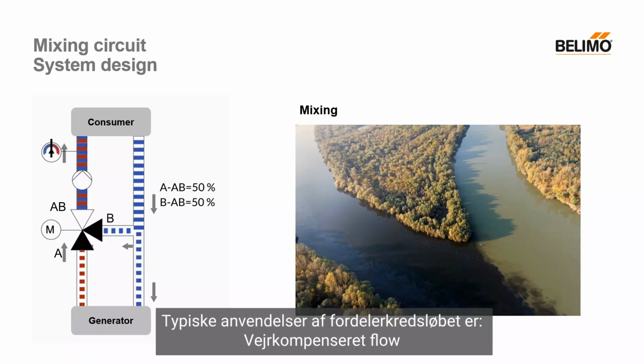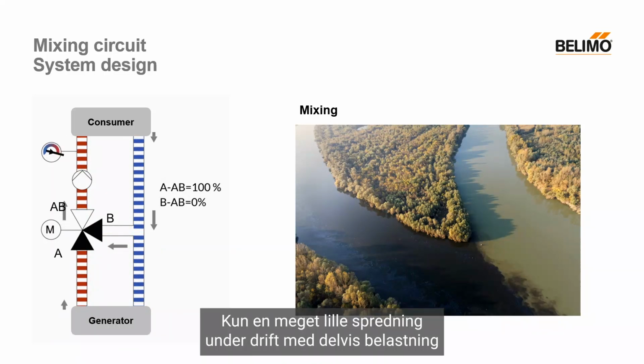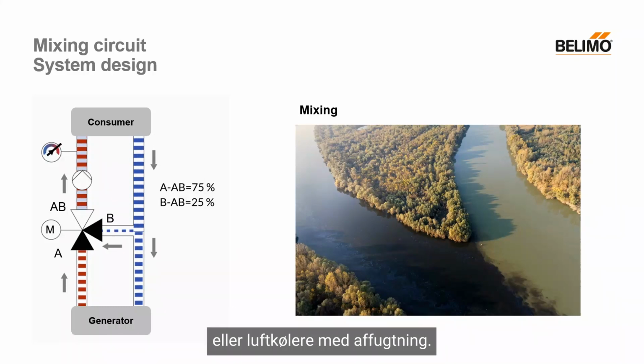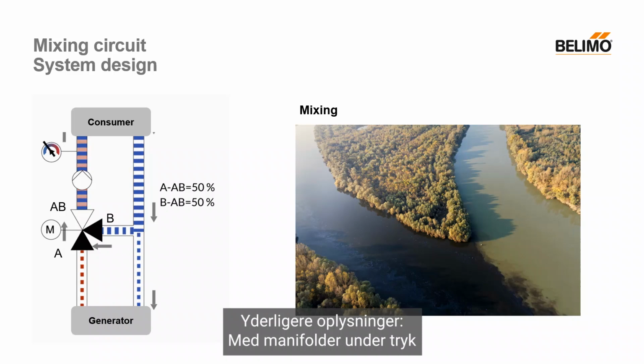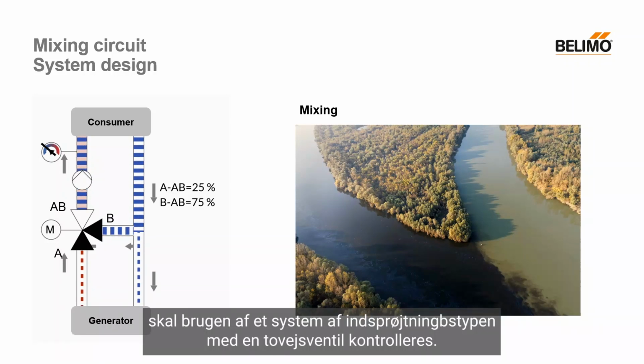Typical applications of the mixing circuit are weather-compensated flow temperature controls, air preheaters, air reheaters with only a very small spread during partial load operation, or air coolers with dehumidification. Additional information: with pressurized manifolds, the use of an injection-type system with a two-way valve must be checked.